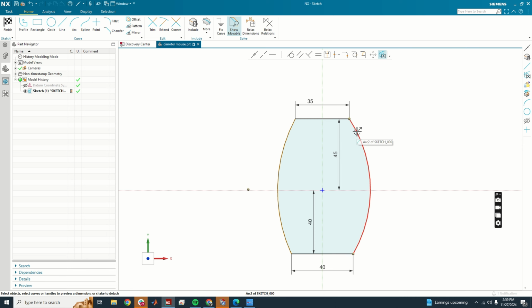like symmetrical. So if I wanted this arc to be as symmetrical as that one, first of all, I'll just define one of the arcs with a radius. Maybe I'll make that 65 millimeters. That's a little bit too big, 75. There you go. So if I want this to be just linked to that, this sketch, it's easy to go up here and select make symmetric.